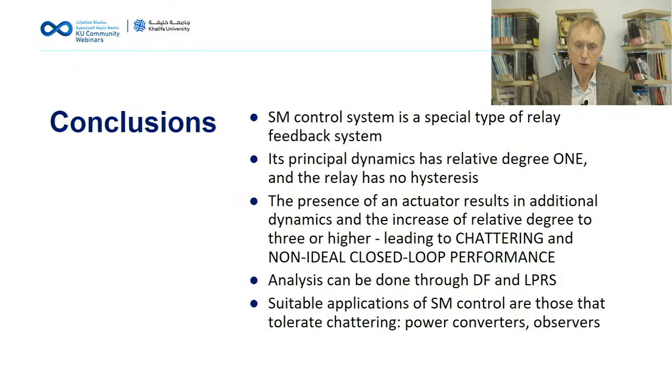And the conclusions. Sliding mode control system is a special type of relay feedback system. Its principal dynamics has relative degree of 1, and the relay in this sliding mode control system has no hysteresis. The presence of actuators and sensors adds relative degree. So this leads to chattering and non-ideal closed loop performance.